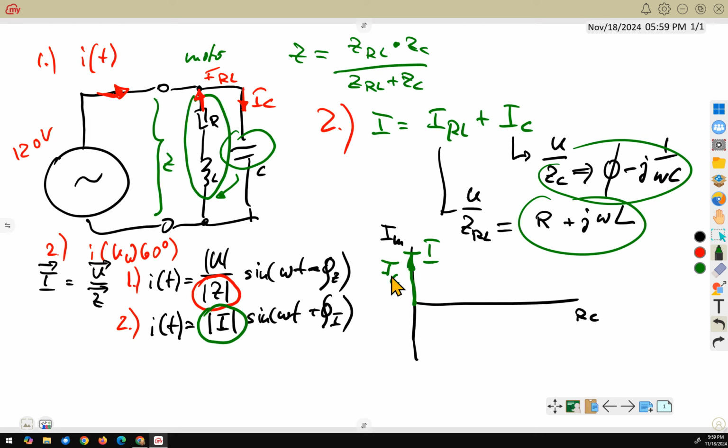The current through our inductor would be negative, like this, but in series with the resistor it's a little bit rotated, so that we actually have here our I of the RL branch. If we do the triangulation and the math in the Cartesian format, we get a resultant current, this one, with an angle phi, which is minus 9.45 degrees.